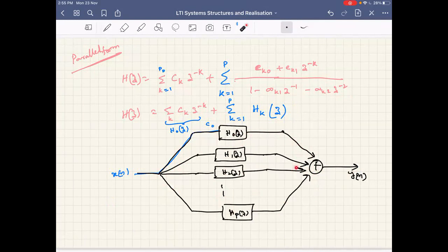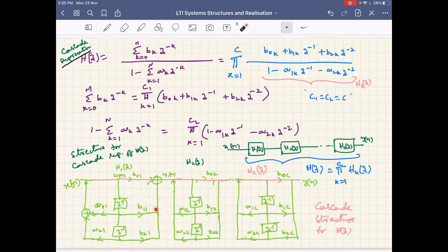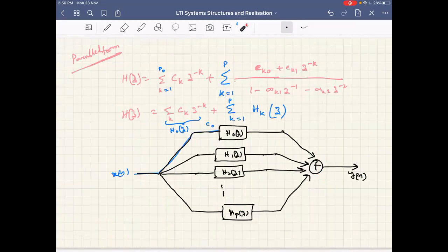As for the stability of this system, the analysis or the implementation through this cascaded form is very useful, because it not only ensures the location of poles, it also visualizes the location of zeros. And the inverse system of H of z can also be easily analyzed if a system is realized in cascaded form. So what will happen if the signal flows from here to here? I suggest you realize this explicitly as homework.